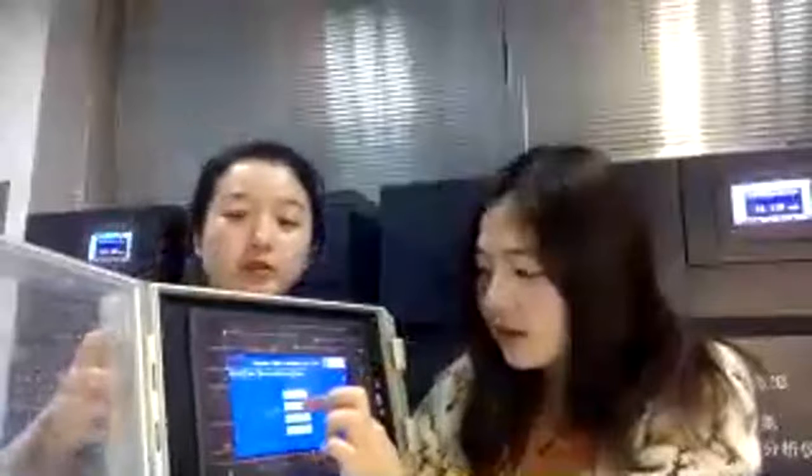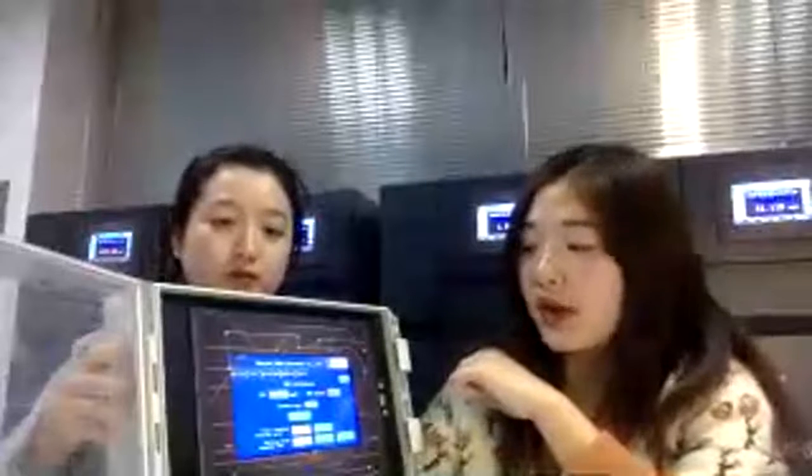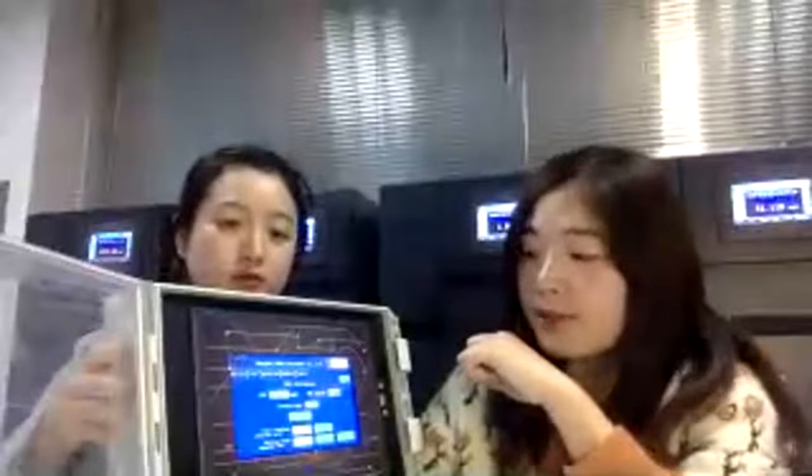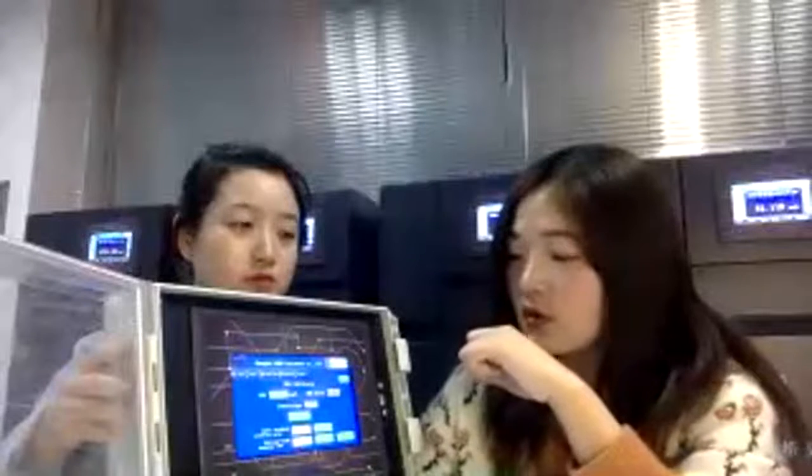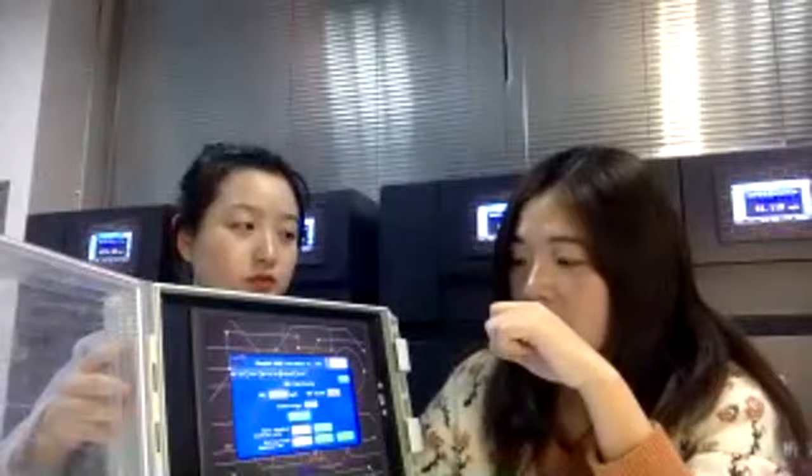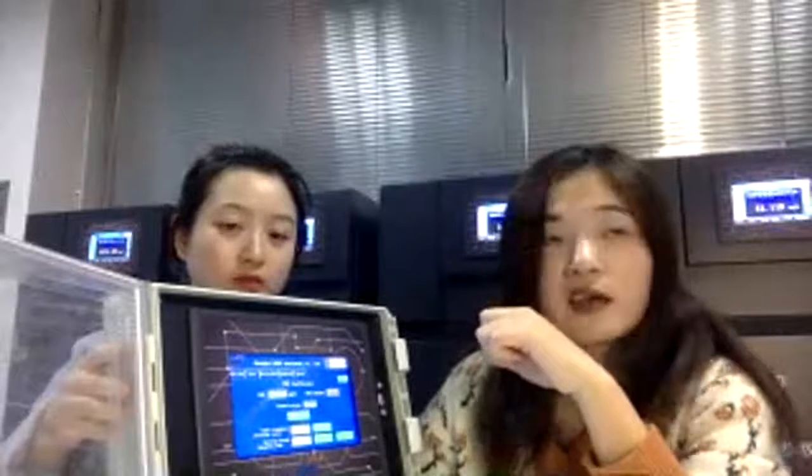So, let's talk more about the TSS calibrate. It is very similar to the pH sensor calibrate. On the TSS calibrate page, we have the measure range for the TSS, the TSS factor, and the communication.